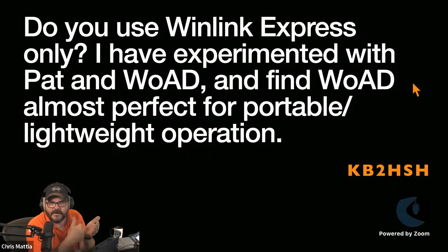The problem is you can either send that traffic via Telnet. You can do it via packet now. There are some different packet protocols. So if you can get into a packet gateway, oftentimes you can get that traffic to go through. If you're trying to do VARA, either VARA FM or VARA HF, then you're going to need a Winlink machine, a Windows machine that's connected to the radio that's got VARA running on it, and then be able to pass that traffic into the Windows PC that is connected to VARA and onto your radio to send it.